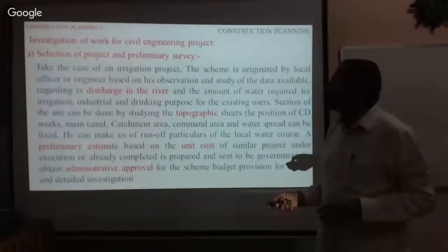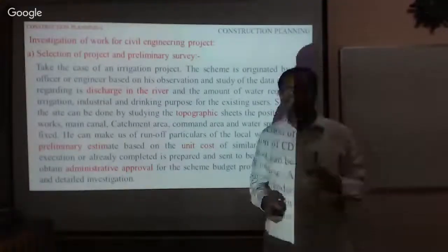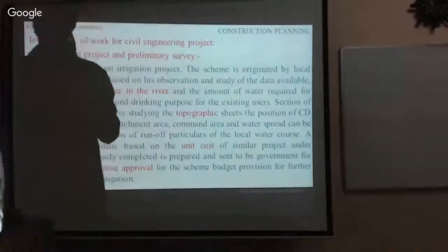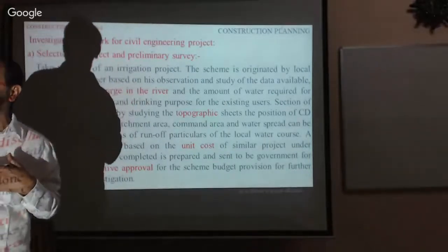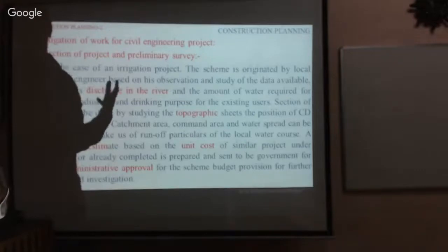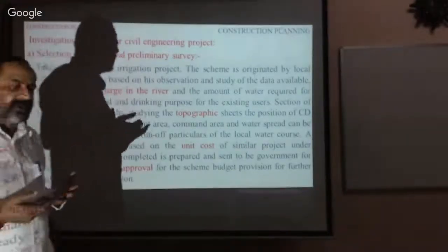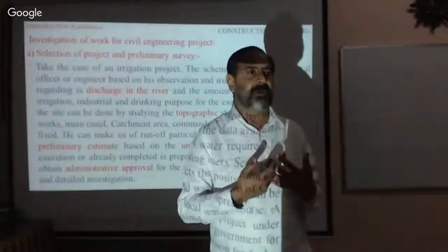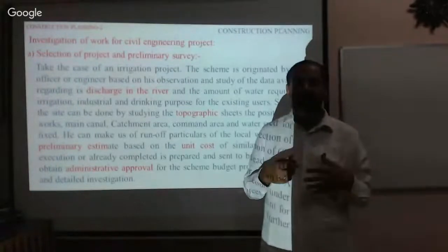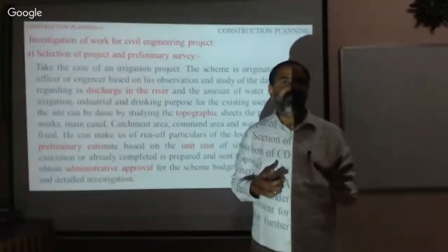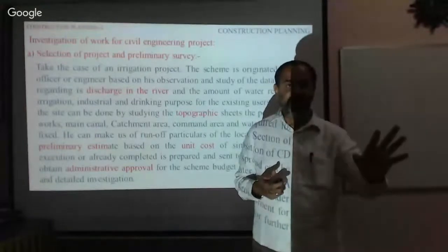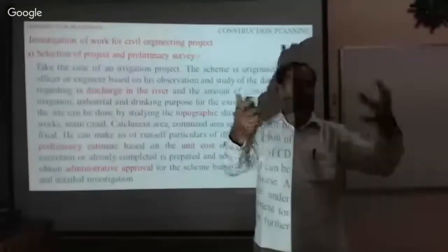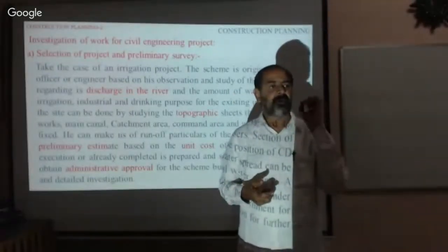Investigation of the civil work in engineering projects is the most important task. If somebody asks you to build a home, he has a lot of money. If I am the owner and I have to build a home of 1,500 square meters, or whatever the quantity may be, and I ask you to get me the project report, you cannot blindly prepare the drawing. First, you go to the site. That is the first job. Go to the site, collect the data, and also assess the material available around the location where you want to build the home.